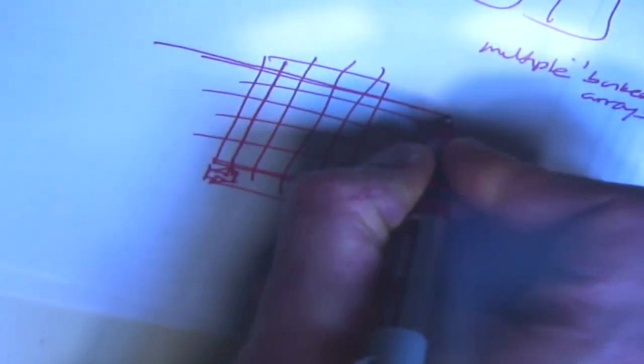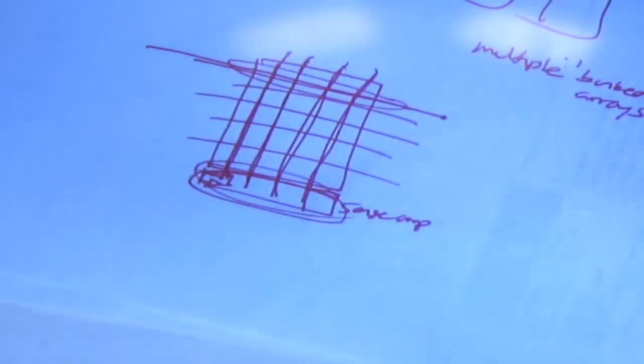Basically, you have word lines, and you have many word lines. These are the rows. And you have many bit lines. These are the columns. To access a row, you activate the row, activate the word line. And the sense amplifiers amplify the data that's on the bit line over here. And then you figure out what the value is in that entire row over here. So that's how it works.